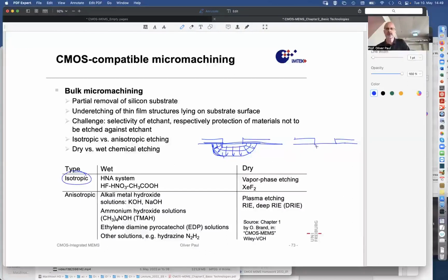as opposed to anisotropic, where the etching takes into account or is influenced rather by etch planes. And so maybe I should even be more precise. I should remove this first surface to say that it has been etched. And so here also there has been some etching, removing of material until which boundary? Until a boundary that might look like this. And so here we have these 1-1-1 planes, of the {1-1-1} family.